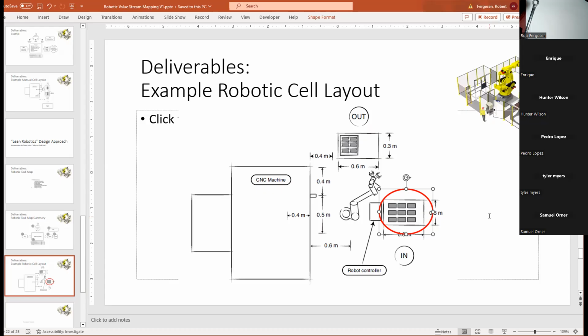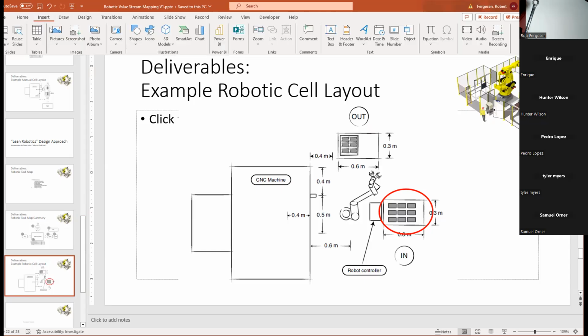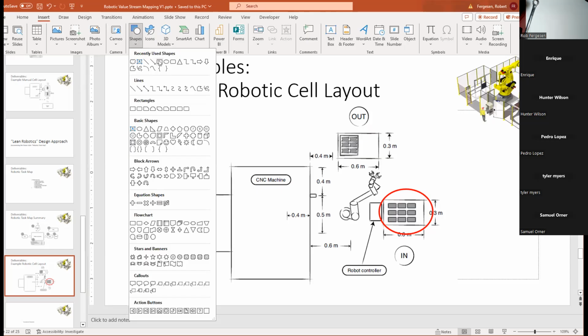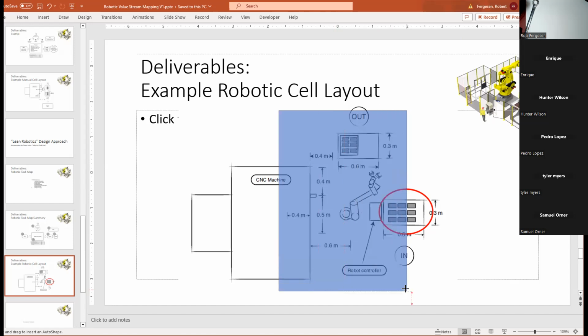In safety, it depends on what kind of robot you've got. If you're using a particular arm robot like the Yaskawa, an industrial robot, you need to do something about this cell. What can you do about this cell? Well, you need to put a fence around the cell. Typically, a fence might look like this.